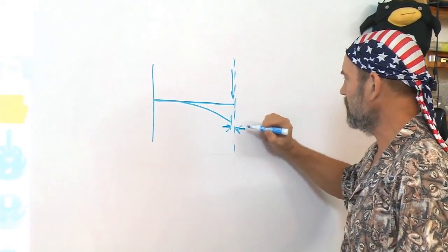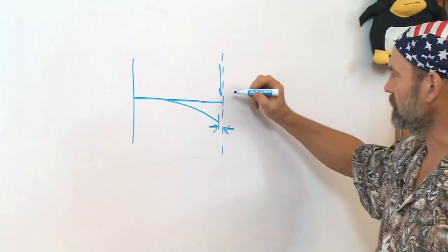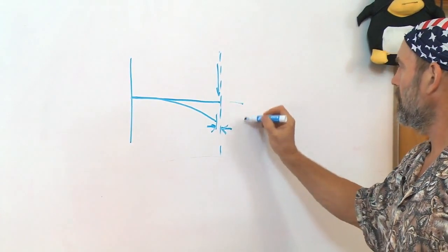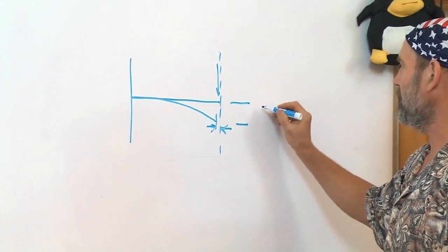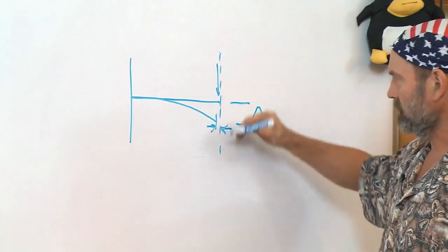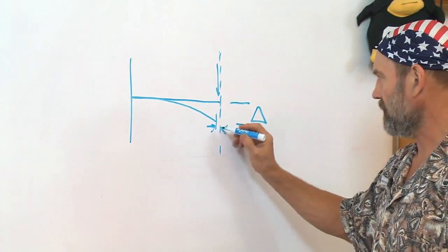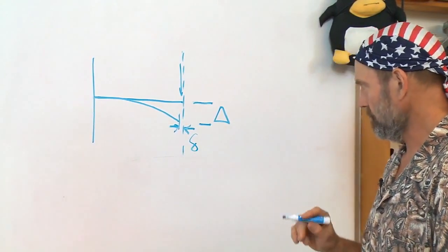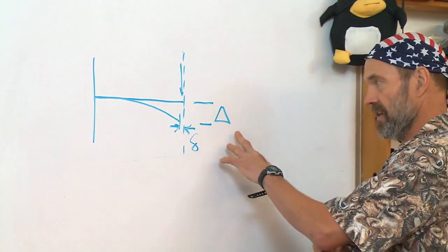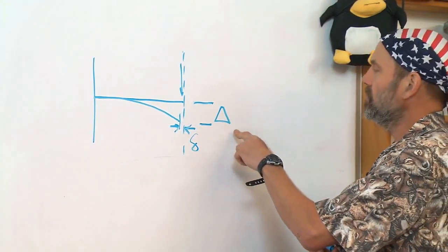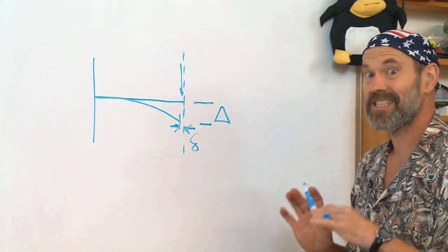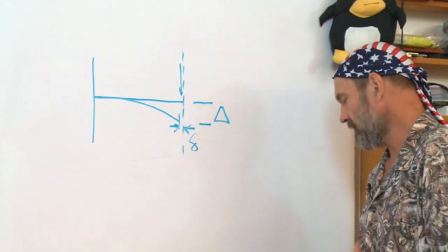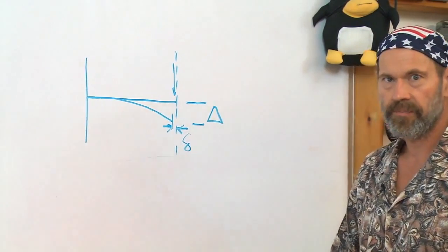You can read the formulas in the text and even their derivation. And that bending of the beam, if the large bending is delta, this little delta is the parasitic motion, because that's usually unwanted. It is typically less than an order of magnitude smaller than the large deflection, but it's there. And for some types of structures, that can be unacceptable.